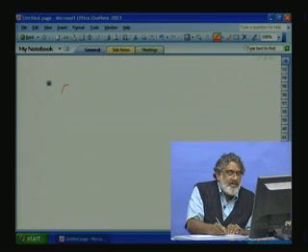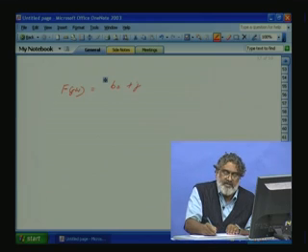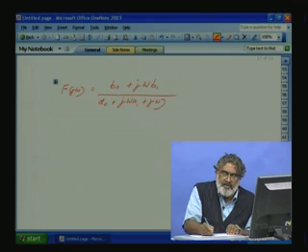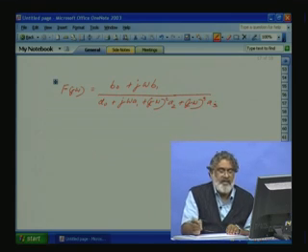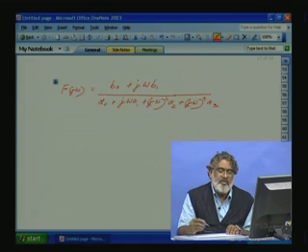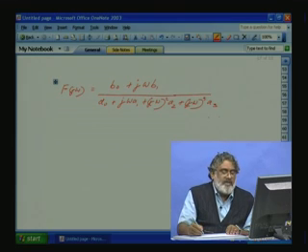For a third order system, Fj omega is B0 plus j omega B1 by A0 plus j omega A1 plus (j omega) square A2 plus (j omega) cube A3. One condition we set from the numerator, but here we are not worried about the numerator in our system, because we are taking care of that by giving a filter to the input, same like our current controller.